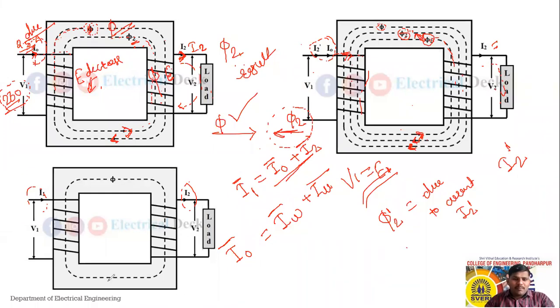And similarly, in case the transformer is put on load, ज्यावेळेस ट्रान्सफॉर्मर लोडला पुट केले, again the supply current, or the primary current taken from the supply, that is I1 bar, is the vector sum of the no load current plus the additional amount of current taken from the supply, that is I2 dash current. So see, from these two, the no load condition and the load condition, we can conclude that whether it is load or no load, the operation of the transformer will be the same.